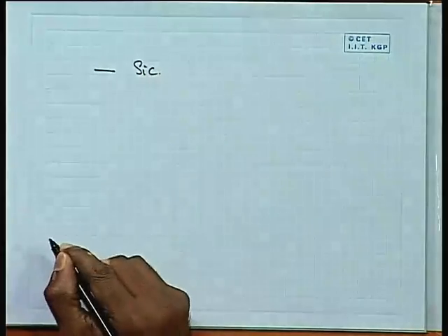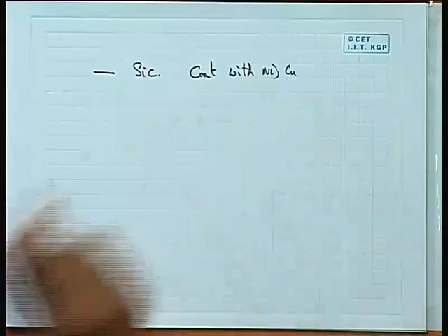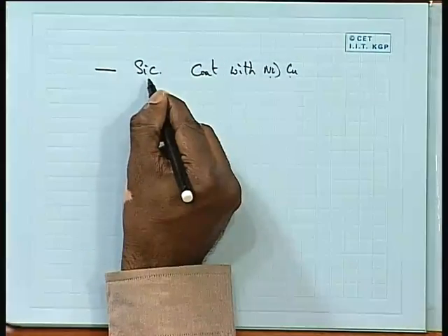People tried to overcome this in two ways. One is to modify the particle. For example, you take silicon carbide particles and coat them with various metals such as nickel, copper, by electroless coating or electroplating kind of techniques. We cannot use normal electroplating because the particles themselves are not conducting in nature. So you have to use other methods such as electroless coating techniques, where people coat nickel, copper and other elements. Once you put these coated silicon carbide particles into an aluminum matrix, the aluminum liquid comes in contact not directly with the silicon carbide particle, but with this coating. As a result, the metal-metal bonding is much stronger, so there can be a better cohesion between the particle and the matrix. So this is one possibility where the reinforcement particle is modified.